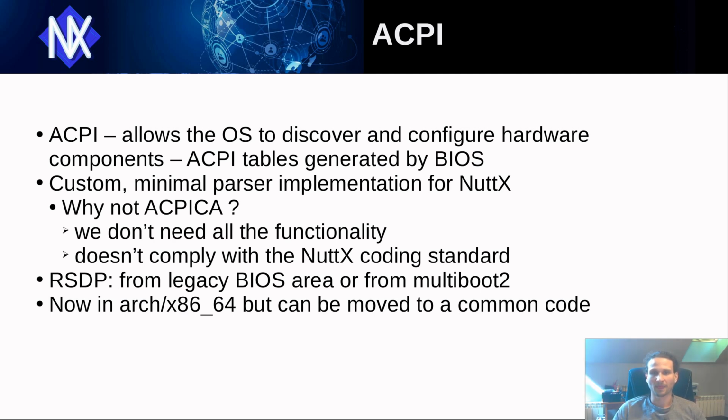So let's start with ACPI support in NuttX. ACPI is a component present in almost all modern computers. It is a standardized interface used to perform power management, device discovery and configuration tasks. For now we are only interested in the hardware components discovery feature. This means that what we need is to extract some data from memory that is provided by BIOS in a format of ACPI tables. That's why a simple custom ACPI parser was implemented.